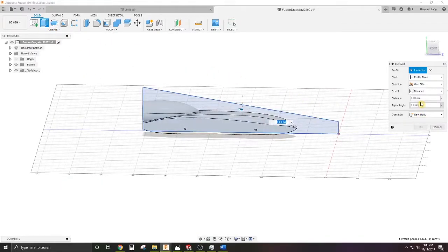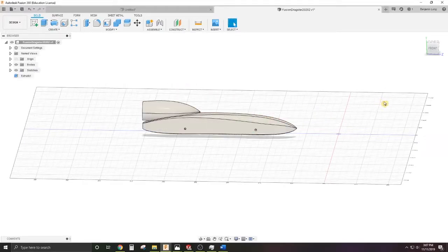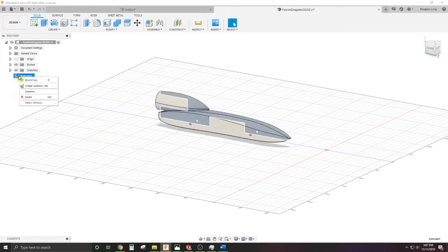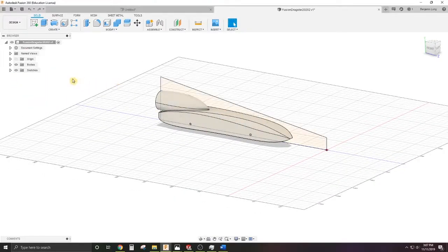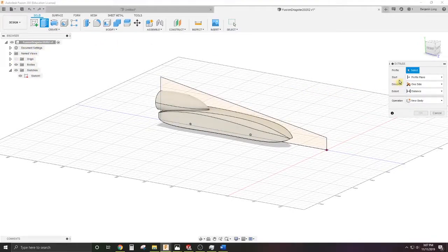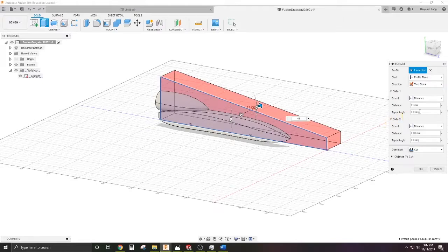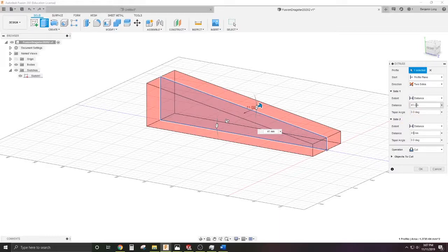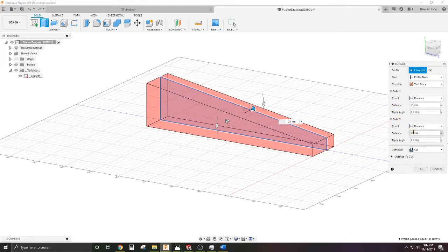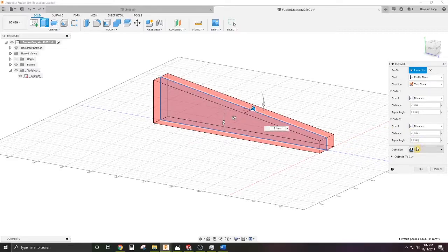So I'm going to go ahead and extrude a 2-side extrusion, and I screwed that extrusion up. That sketch should still be there. Okay, so I undid, or Control Z'd, that extrusion. I hit enter too quickly there. So I'm going to select my sketch. I'm going to select 2 sides, 41 in that direction, 41 in that direction on both sides. Oh, sorry, 21 and 21 to equal 42 total millimeters.